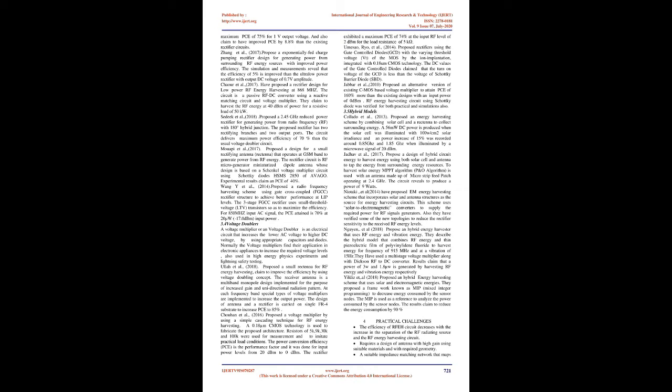Hamid et al., 2013, proposed an RF-DC rectifier using a passive multi-stage circuit implemented on standard PMOS transistors to allow individual bulk biasing and thus avoiding the necessity of deep NWELL technology. The proposed 915 MHz rectifier is fabricated with 130 nm CMOS technology. The design is capable of generating 1 V output with a received power of -22 dBm.